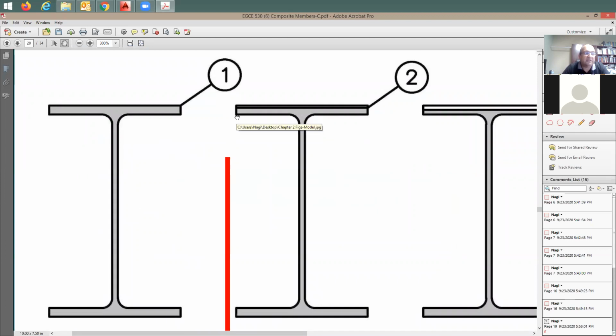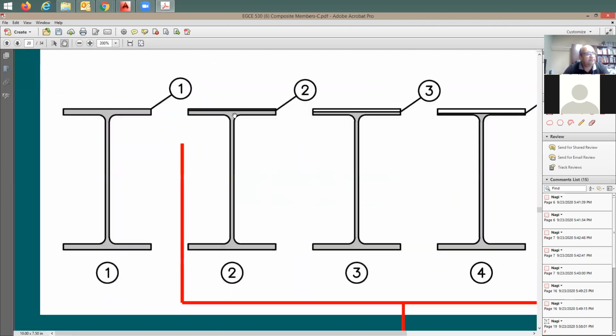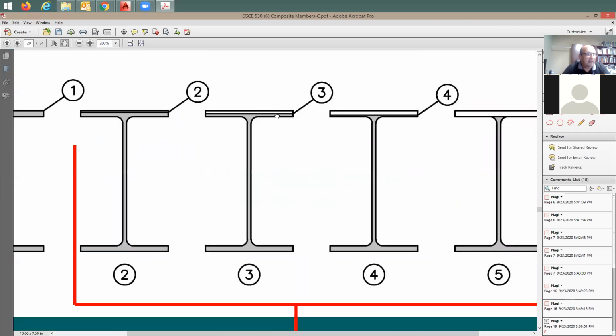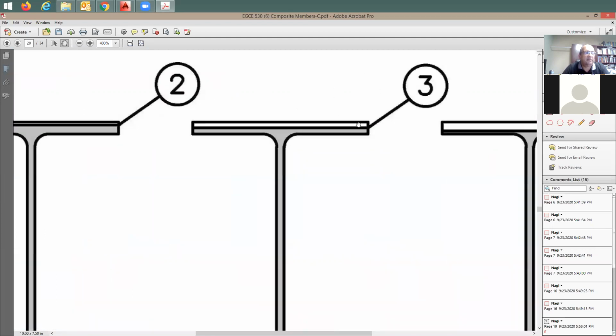I guess if you do this by hand, it's going to be really tough. This is why this table is much easier than using hand calculation. How about in point 3? In point 3, the amount of steel cross-section area that you're utilizing is going to be equal to As of the entire steel section, subtracting 1/2 of the flange thickness. So this shaded area is going to be the area that I'm going to be using in my analysis.